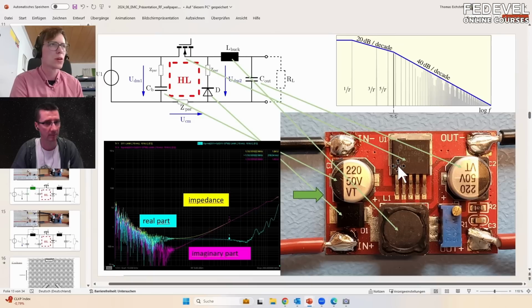And the big IC which you can see here, this is actually the switch. And this creates now out of 12 volts a 5 volt at the output. What is the current for the output? Yeah, this depends in which range you use it. I have at the moment, I think, about 1 ampere, but this is not the limit which we actually have here. Okay. And so what is wrong with this board?